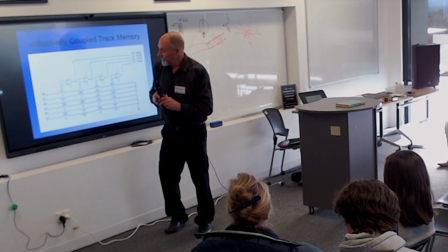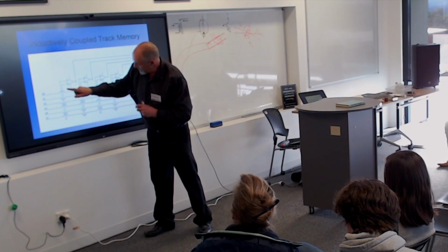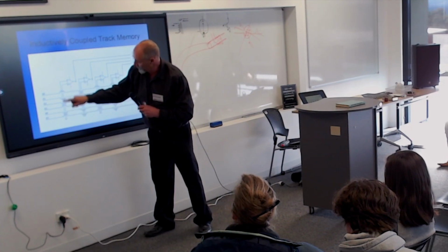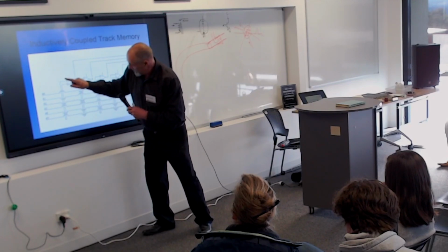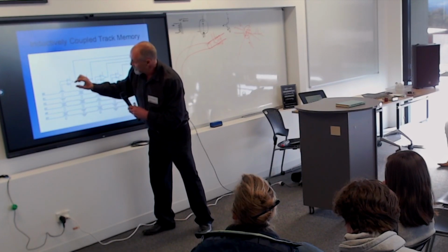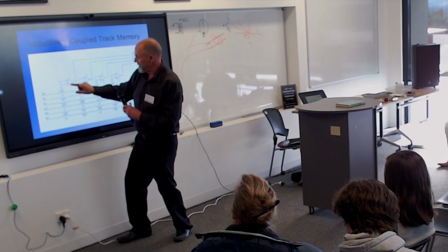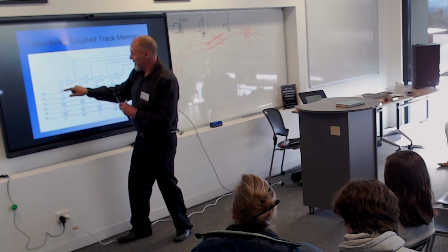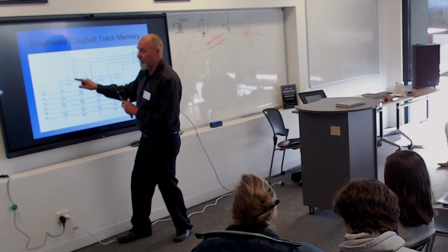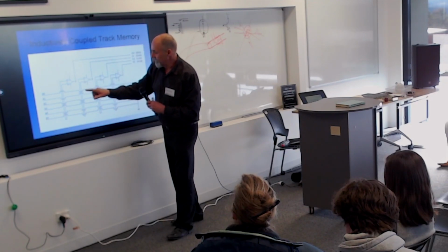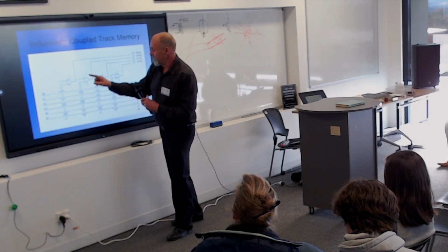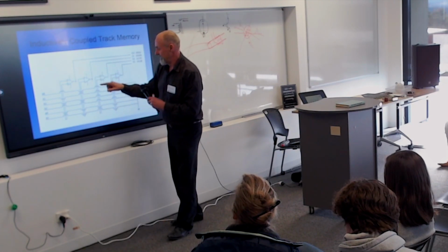So it's induced a current. This piece of wire is basically a loop. There actually should be a resistor here. So I've generated a voltage across this differential amplifier because it's going this way. That pulses positive. And over here, it's going the other way. So this one pulses negative.